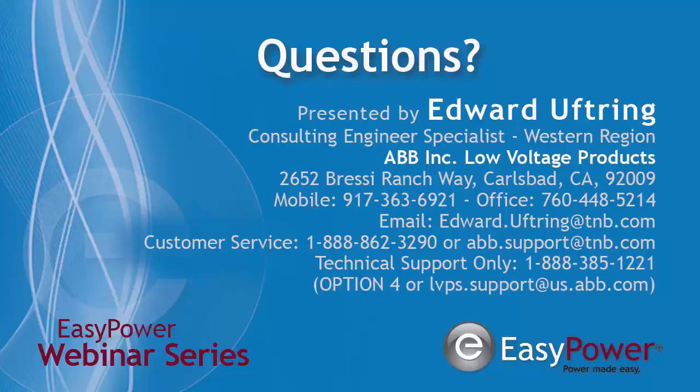The I squared T is basically the let-through energy. The question was, can you please explain the I squared T feature on the MCCB again? So I squared T is power. It's basically how much power, how much energy is going through the device. Current limiting devices make sure that the time is reduced such that the power is reduced.